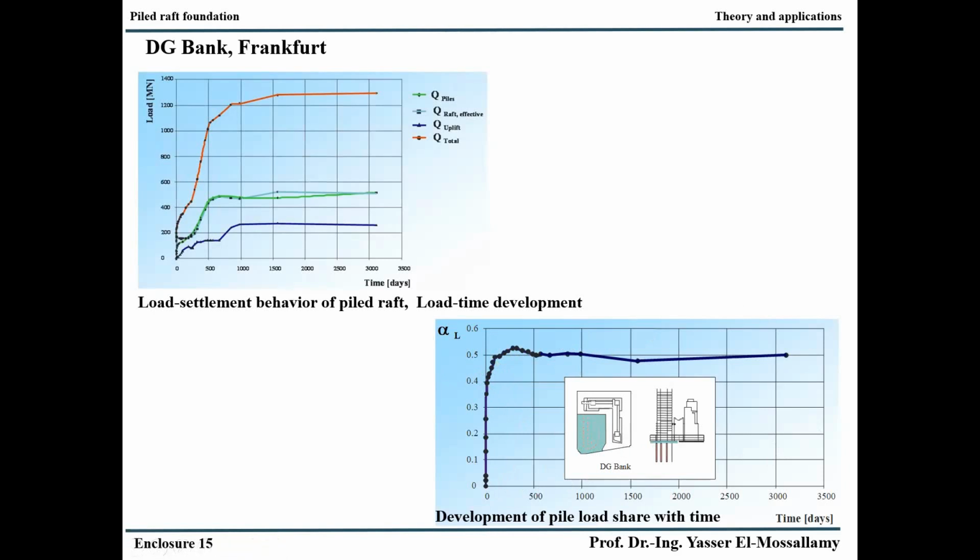That means consolidation and creep of the clay doesn't affect the factor alpha L, and this is a very important design criterion. Of course, this is very special for over-consolidated clay. If we apply a piled raft foundation in soft clay, then creep and consolidation may affect the load sharing between the raft and the piles during the lifetime of the building, and we should consider that in the design so that the structural actions in the raft are well covered in all conditions.